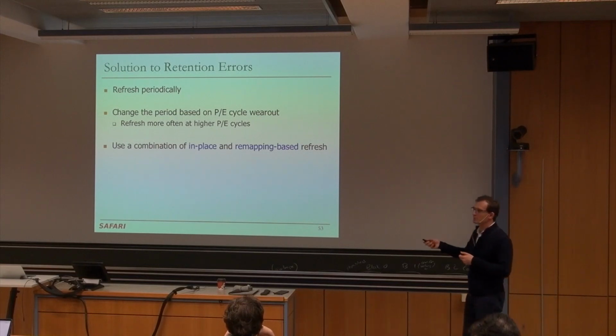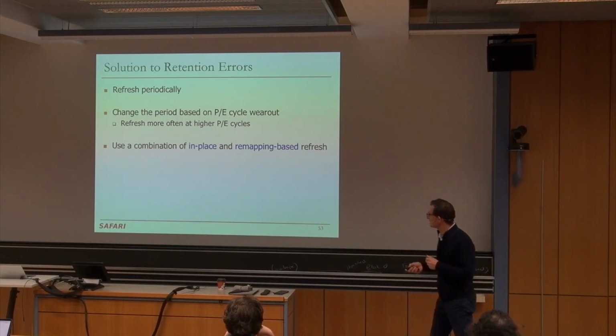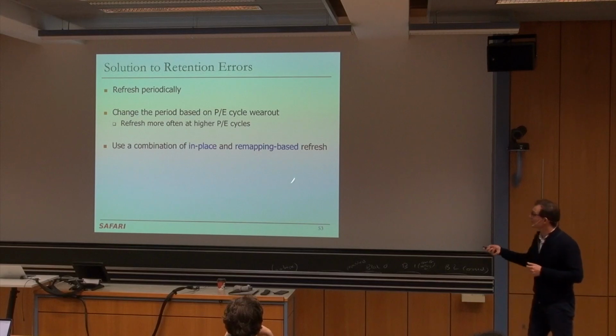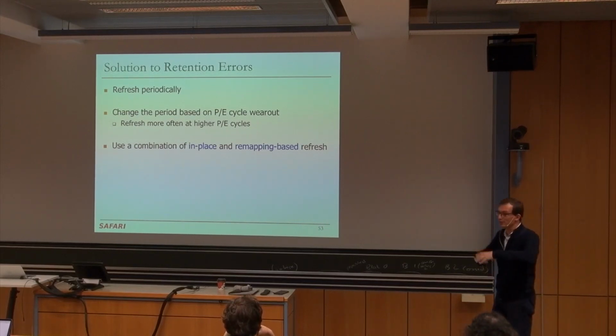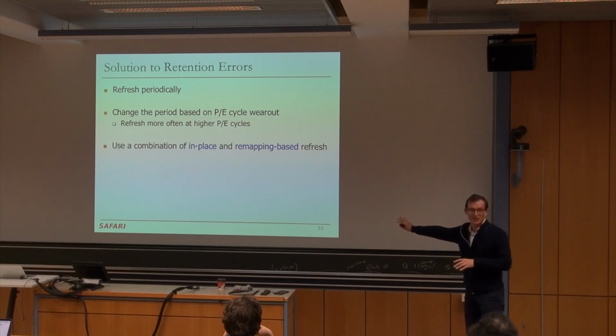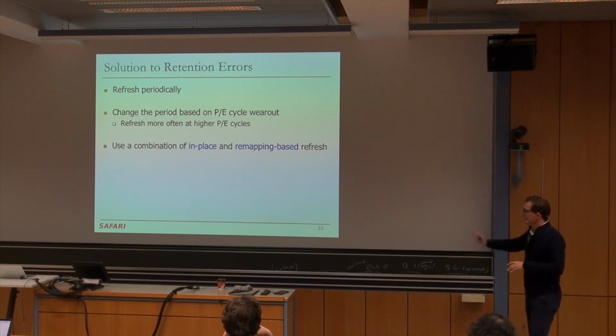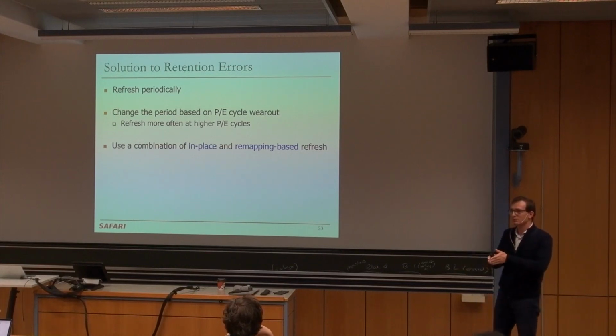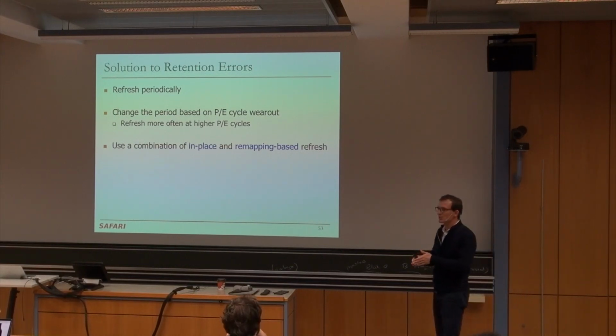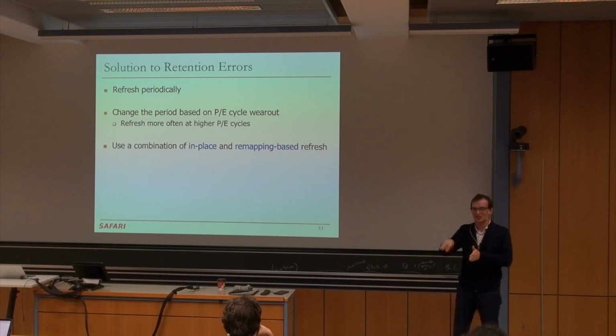So that's one of the ideas that's employed in existing drives right now, but that may not always be a good thing. Sometimes you may want to remap this particular page or all of the pages in this block to some other place. And we'll see the trade-off between them, because if you do in-place programming and increase the voltages, you're causing program errors to adjacent pages.